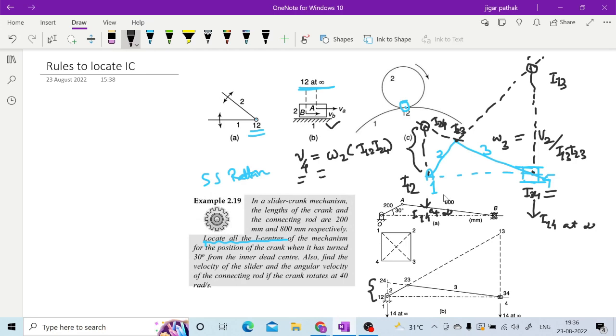Sorry, 1 and 4. It's totally linked, na. Isn't it linked? Yeah. 1 and 4 are linked, but it is linked this way as mentioned in this figure B. One is fixed and the other is sliding. So whenever you have this kind of combination, the instantaneous center of rotation will go at infinity. Whenever it's linked between one fixed and one sliding, then that would be infinity, right, sir? Yes. Okay, sir. Okay. Thank you.